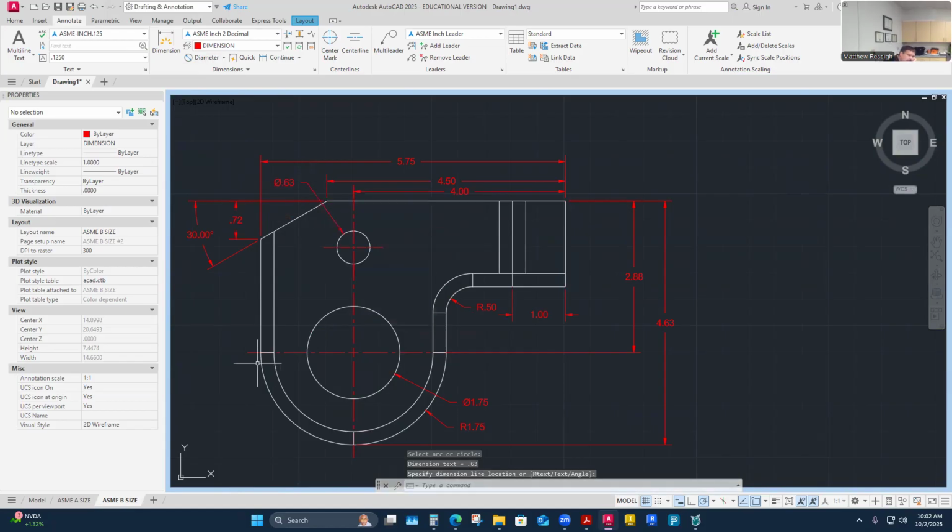0.63 is what it is. I think our print called it out 0.625. And I'll come back and think about that once I'm done here, and make sure that I haven't inferred less accuracy than I was given. So that's something to think about. Remember, I'm holding to 2 decimal places. So let's come back to that later.